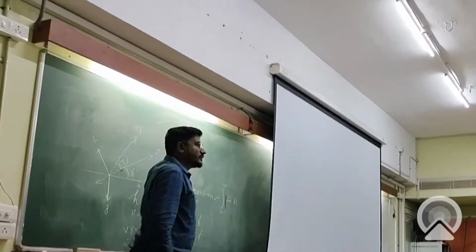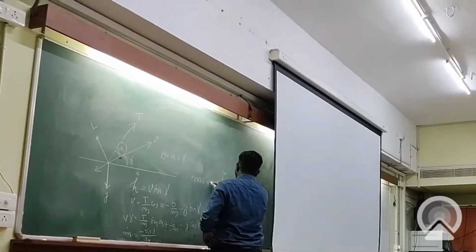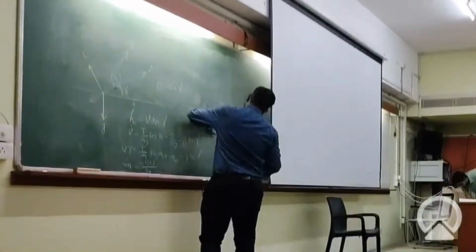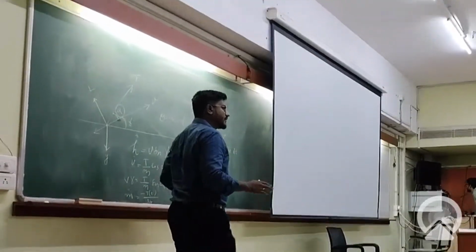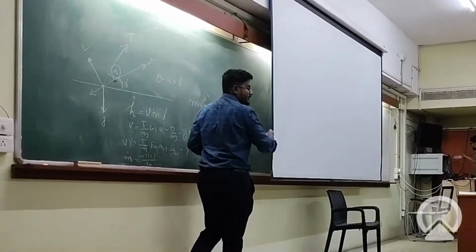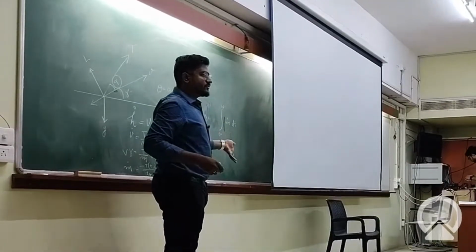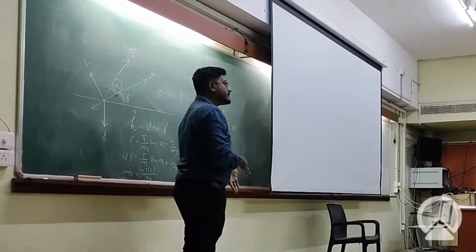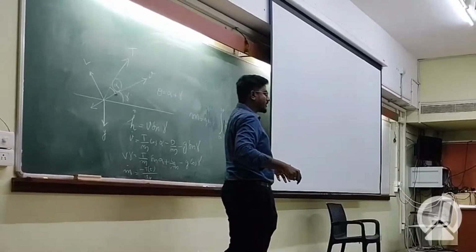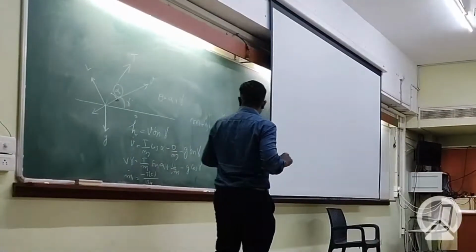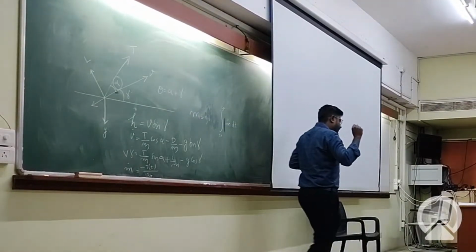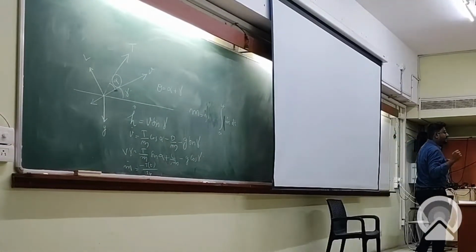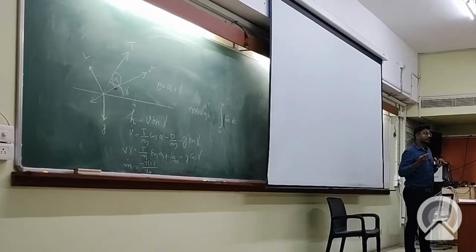We are trying to maximize m0, the lift-off mass. So basically, the integral from t0 to tf of m dot dt is what we're trying to minimize. This is nothing but the mass expense, right? The dry mass is fixed. So if you minimize the mass that is being ejected out of the rocket, ultimately you end up maximizing the payload, right? Now let me bring another perspective. Okay, you know what is impulse? What is impulse?